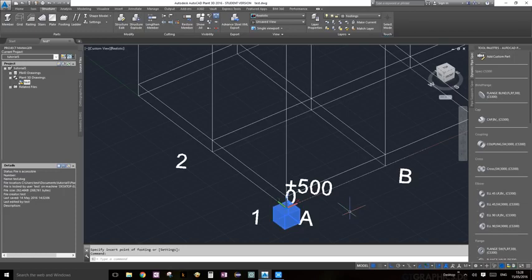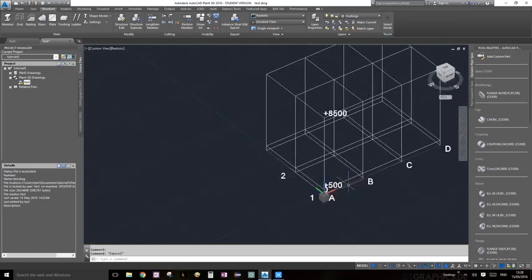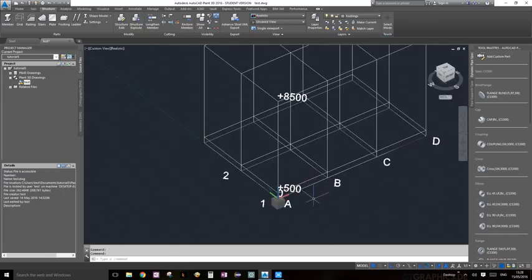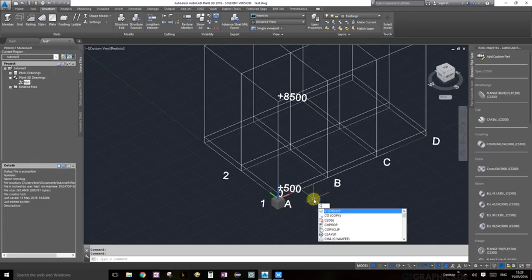We can just select it, and here I'll show you guys how to use the copy. The easiest way to use the copy command is start typing CO or COP. See, the first option that shows up is copy. One thing awesome about AutoCAD is anytime you want to do something, let's say you want to rotate something, just start typing. You don't have to select anything. Type ROT, and see, rotate shows up right by the cursor, and so you can choose which one applies to you.